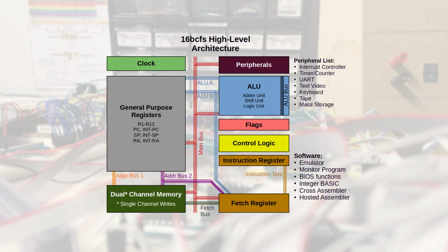With three separate portions of the ALU wanting to feed the results onto the main bus, and me having to calculate flags based on the results of any given operational unit, I originally started out by creating an ALU internal results bus. That even remains on the high-level design graphic that I use between video segments today. There's another solution I want to consider.